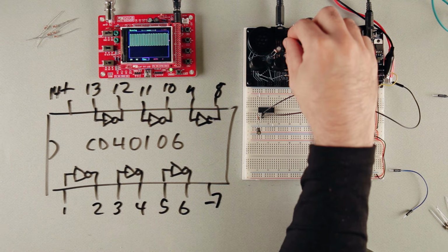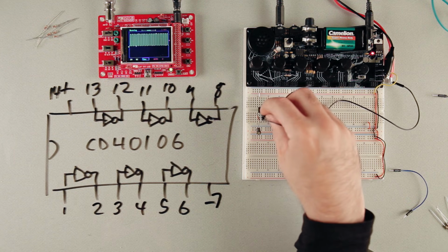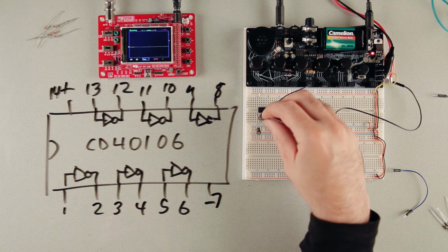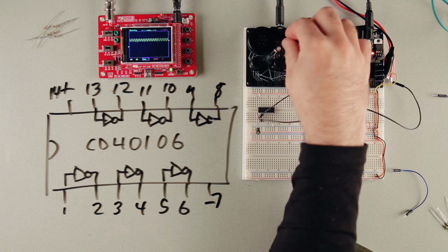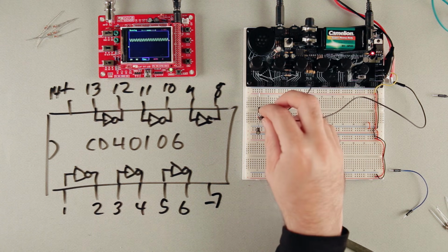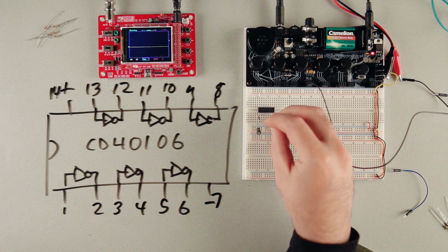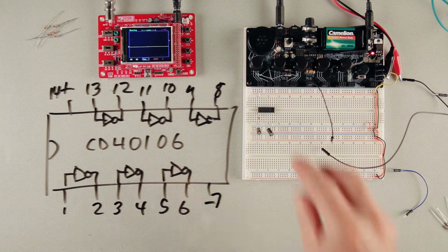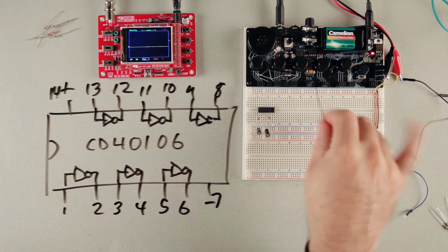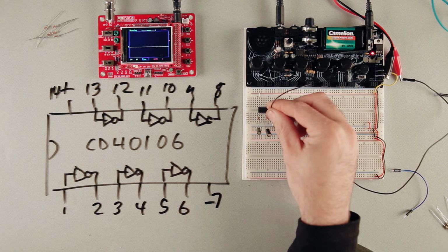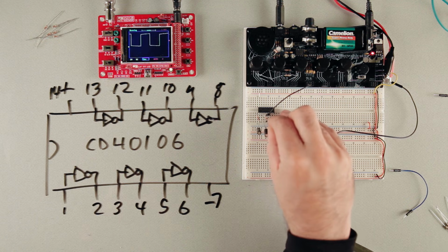So here's the square wave, which you can see here. We can also get a triangle wave, which we can look at there. It's much quieter, but it's a triangle wave. And if we want to make another one, we just need 2 more components, another capacitor and another resistor. And if we listen to that, we've got another oscillator. This one is obviously a much lower pitch.